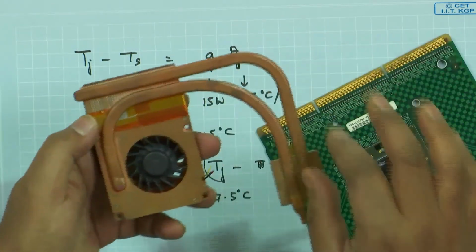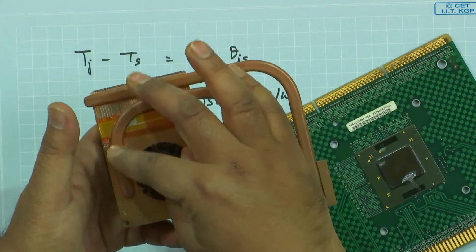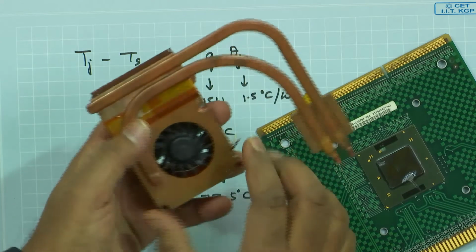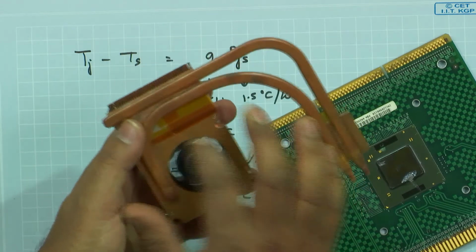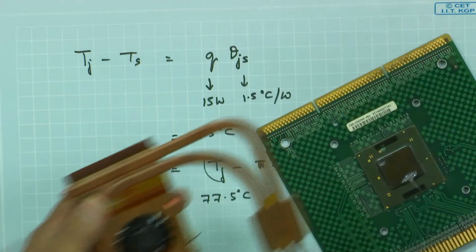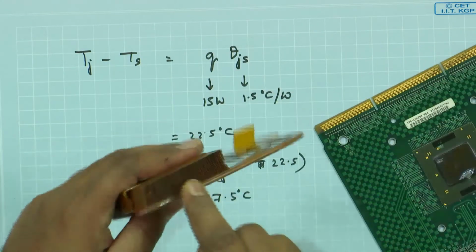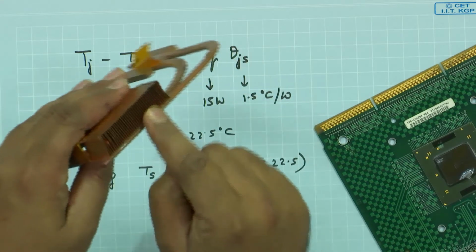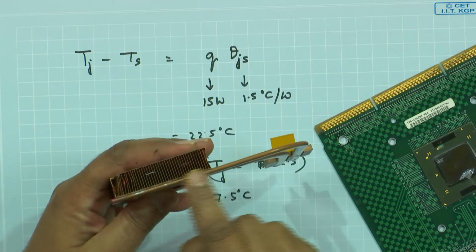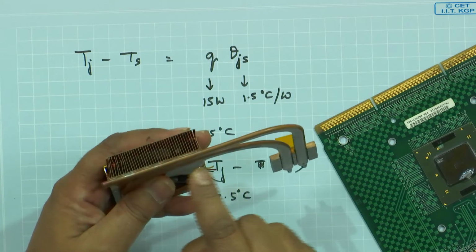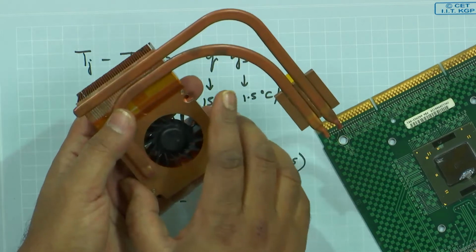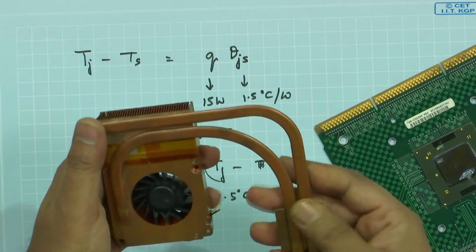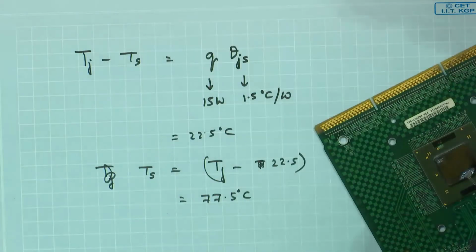Then at one end, these heat pipes are connected to a heat sink like this, through which a fan blows air. As this fan rotates, air comes out. Look at any laptop, at the exhaust vent from where hot air comes out. If you look through, you will be able to see this fin array, and upstream of that is typically a fan. Why do I need this arrangement? I will come to that, but I will just let this get passed on.